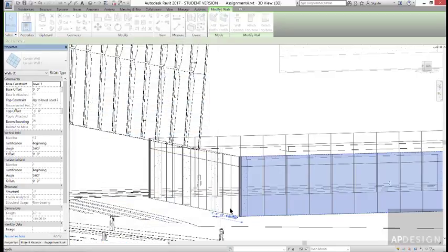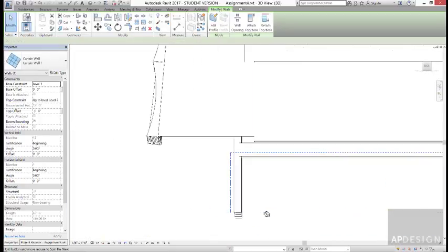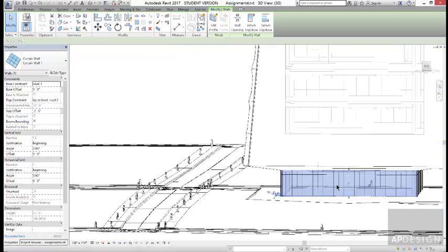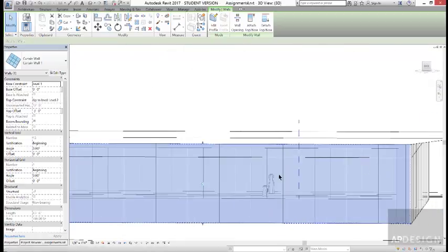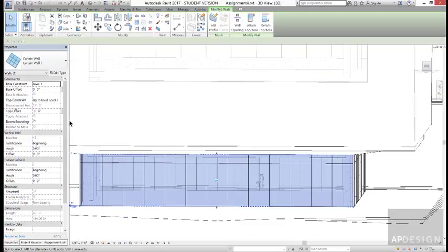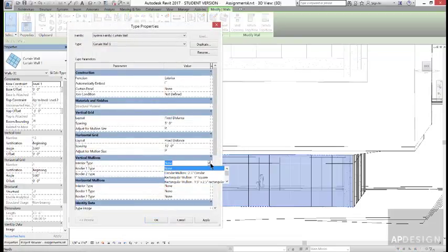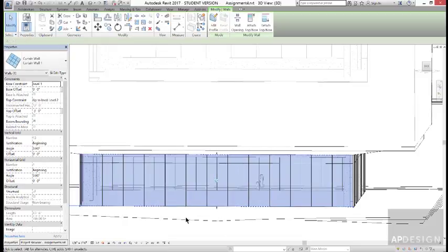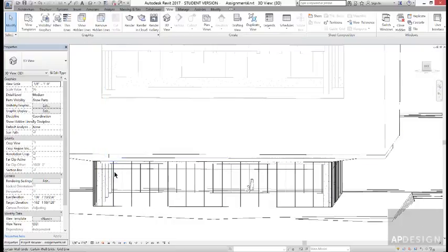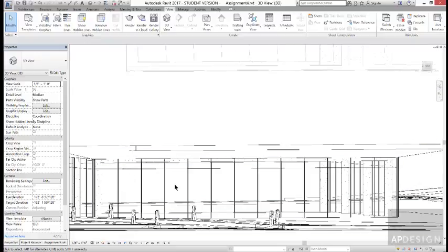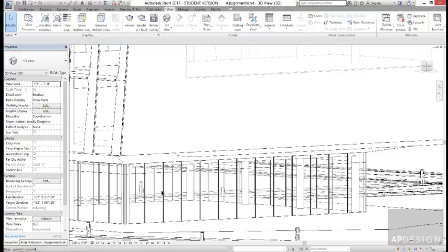So in the border, you can see it's added a mullion right there, and it's more than likely done it here on the other side. But it hasn't touched the middle parts, and the reason for that is that is the interior type. So it could be that you'd want a thinner mullion for those. Now, of course, all of this will depend on how far you're spanning, if you have any back structure kind of holding things together. This isn't spanning that much, so we might actually get away with this thinner type.